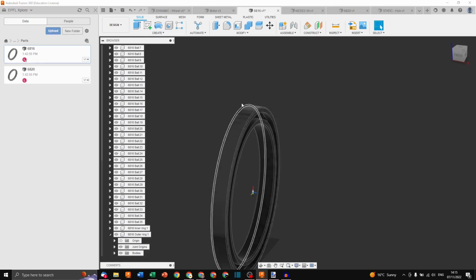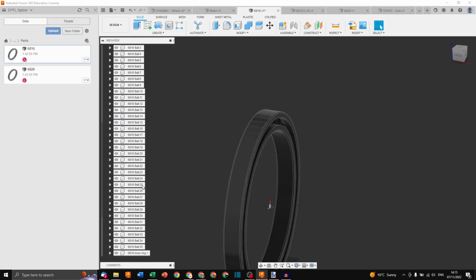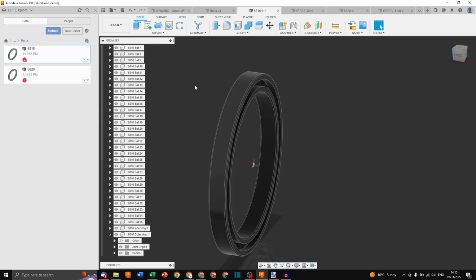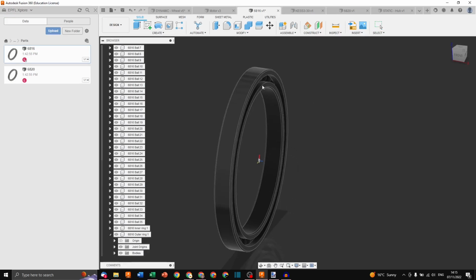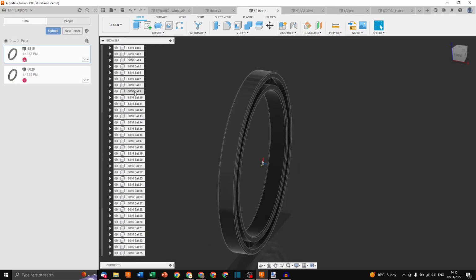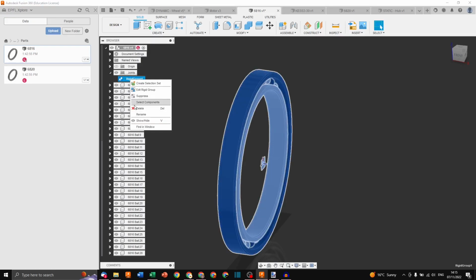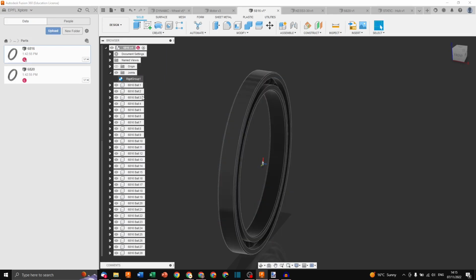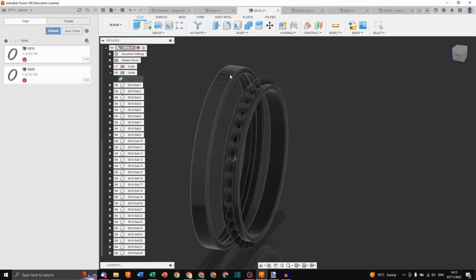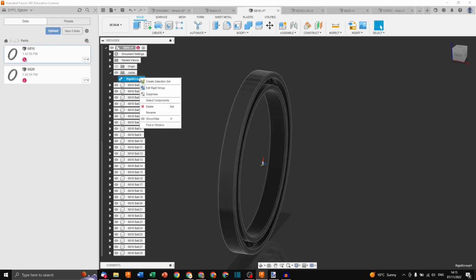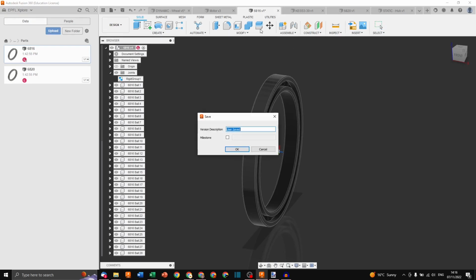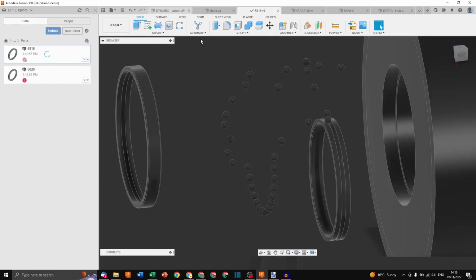Great. So I've now got an inner rigid group and one single joint origin. You can see now, if I try to move it, I can't. I'm moving the whole part, not just one ball. That's because it's got a rigid group. So if I want to rearrange it, I need to remove the rigid group by clicking either delete or suppress. Suppress will remove it just for a moment to let me remove just one or two parts. And then I can press unsuppress and it goes back.